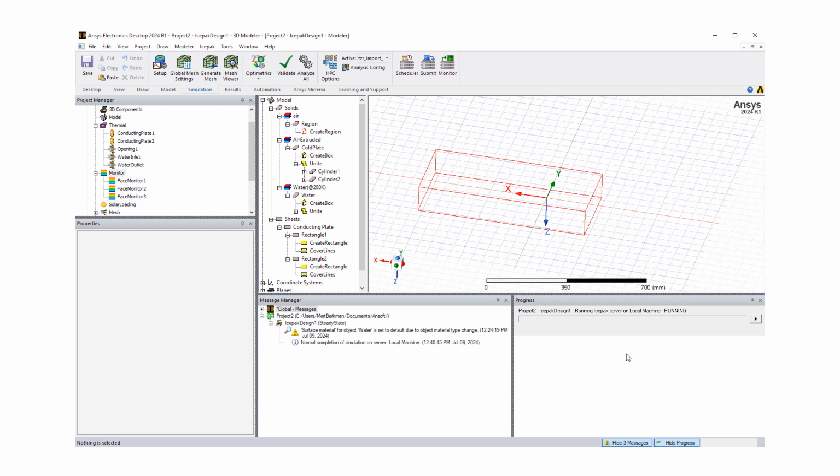As you know, in the background, the Ansys Fluent CFD solver is being used. Once the run is complete, Fluent is going to write out the results, and then they're going to be imported back into Icepak. If there are any problems, we're going to see some messages here, with some bad news. But what we're seeing is it's going through iterations. You can see it's around 110 iterations there. If it doesn't meet the convergence criteria within 300, it's going to run all the way up to 300 iterations and then write the results. And it looks like it's going to go all the way to the 300 limit.